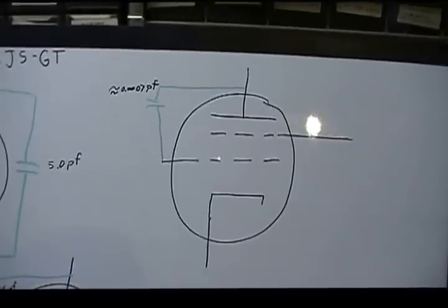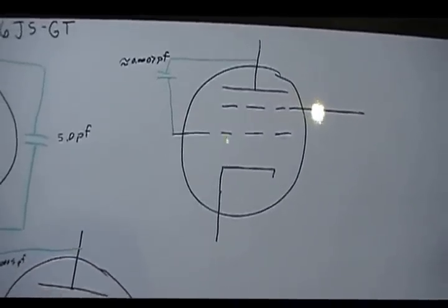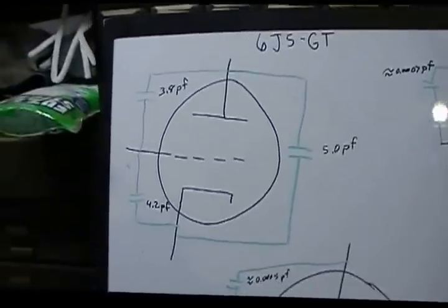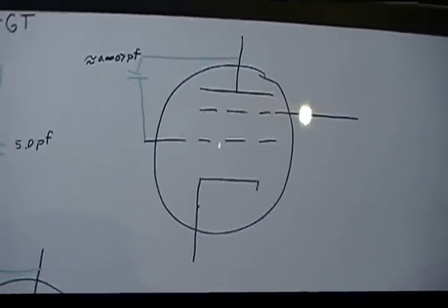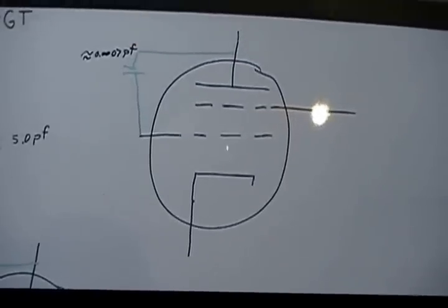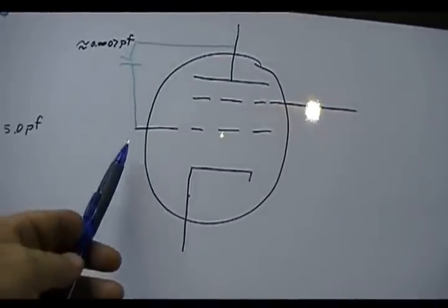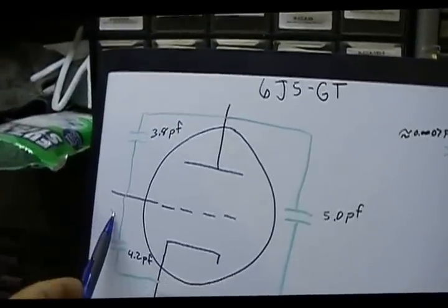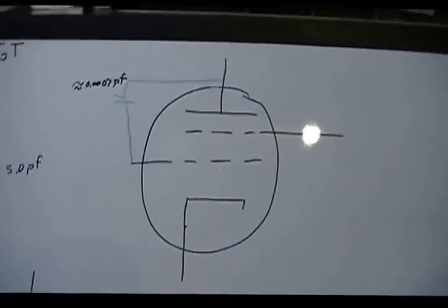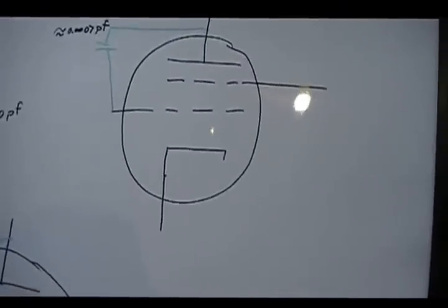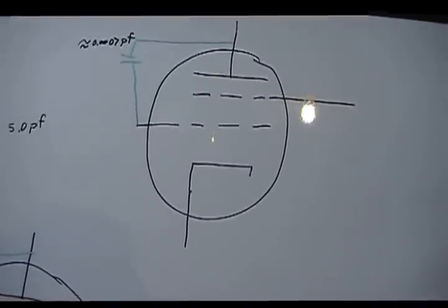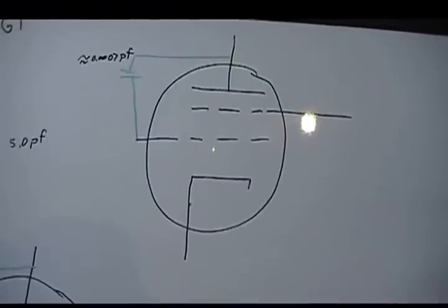So quite a bit higher mu, more than 6 times the value of a high mu Triode, which also means they're more power sensitive. As a power amplifier, it would take a lot less voltage to have the same output as it would for the Triode, which makes designing a circuit a lot easier, and picking the tubes right.